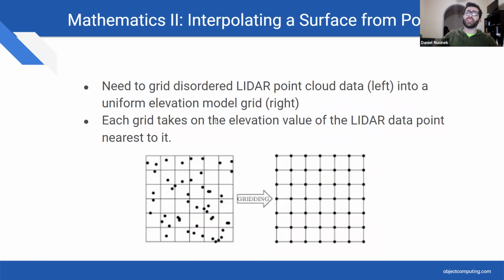And as you can imagine, these files are huge. They're gigabytes each, at least. So one of the easiest ways to work with them is to grid them into evenly spaced raster pixelated images. So for each grid, basically, you assign one elevation value to each pixel, and the pixel width and height are pretty much what you want, maybe 0.5 meter by 0.5 meter. So each pixel would represent 0.5 meter by 0.5 meter, or 1/3 of a meter by 1/3 of a meter. And that's a resolution that's set by the instrument. Like if you're using any satellite, like Landsat, they'll always tell you what the resolution is on the images that they give you.